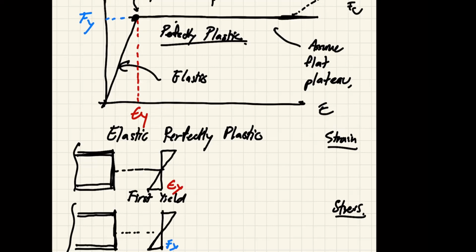But because this is just the first yield, people discovered that you can actually punish your flexural members a little bit more. So we can continue after we reach the first yield. What will happen if we continue on? Your strain will keep going, correct? Because your strain can just go forever. So if I draw the strain diagram, it may just exceed the first yield.